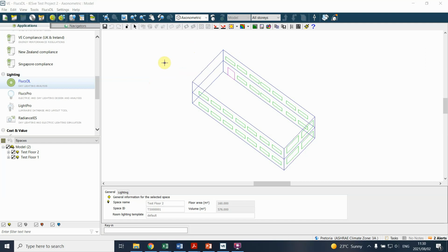So again, you can do this analysis without going through the initial protocol that I've defined, the whole modeling the site, locating the site, and then going through all the inputs and so forth. What is critical though is you do need geometry, as you can see. So the building, or the space, must be modeled. Then it must be located. The weather file is not as critical here, but the actual longitudinal and latitudinal position is really important.